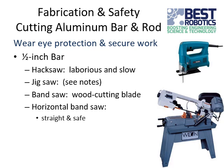For cutting the aluminum, this is specifically talking about the aluminum bar and aluminum rod. Those are the thicker pieces of aluminum. There are several different ways you can do it. A hacksaw is actually, I think, a really good way to do it. Sure, it's a little bit slow. You've got to put in some muscle power for it, but